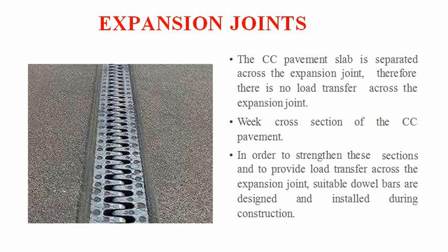Greater the distance between the expansion joints, greater will be the width of the gap for the expansion. The use of a wide expansion joint space should be avoided, as it would be difficult to keep them properly filled in when the gap widens during the winter season.